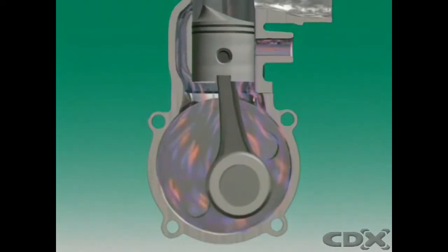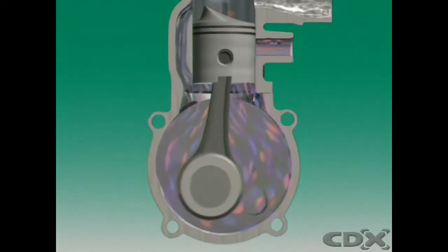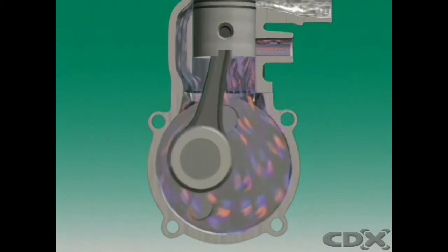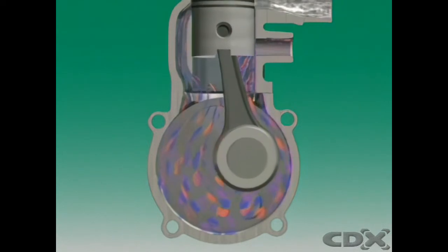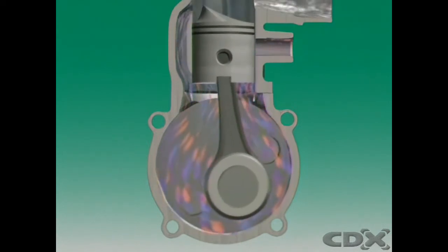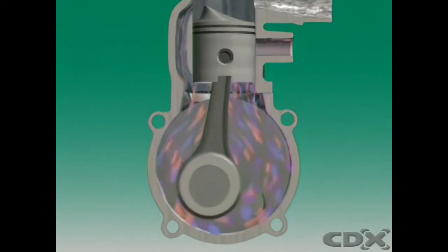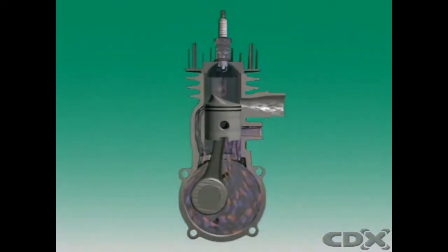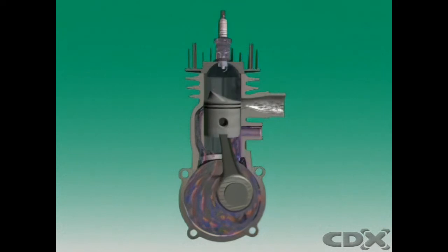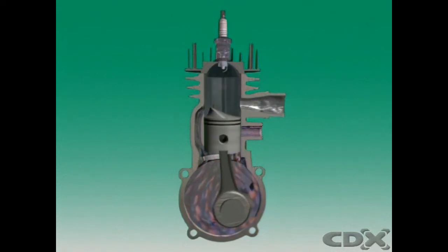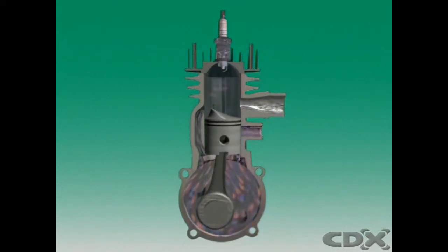A mixture of air, oil, and fuel passes through a sealed crankcase on its way to the combustion chamber. That makes the crankcase part of the fuel intake system, so it can't be used as a sump. As the air, fuel, and oil enter the crankcase, the fuel evaporates, leaving behind enough oil to keep parts coated and lubricated.